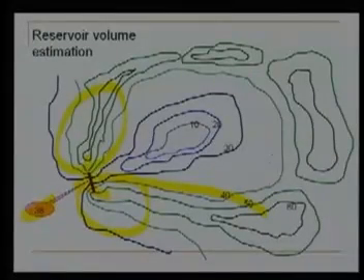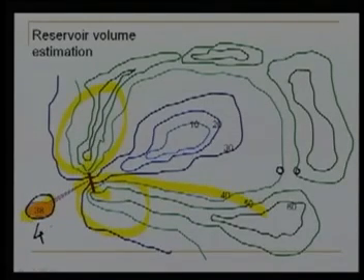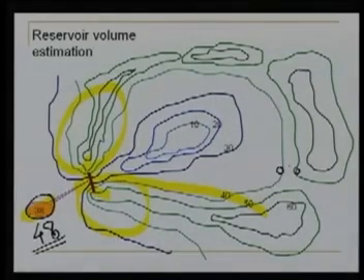Because what we need to do is draw a contour of 38 meter. How to draw that contour? Well, we can make use of the existing contours. Here is a contour of 40 meter and this is the contour of 50 meter. Let us say this is not 38, rather it is 48, as per the drawing. Now this is 40 and this is 50 meter, so the 48 meter contour should be somewhere here.